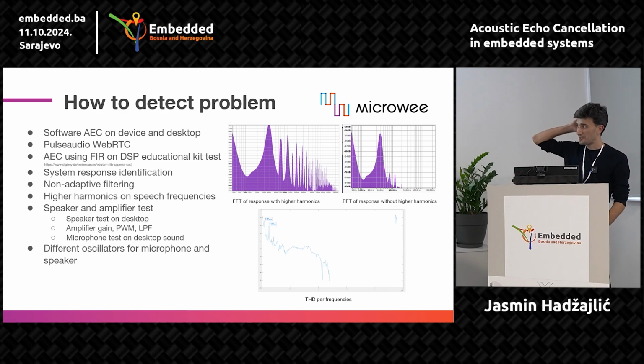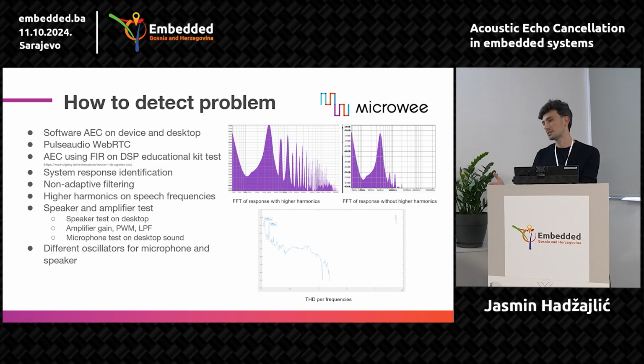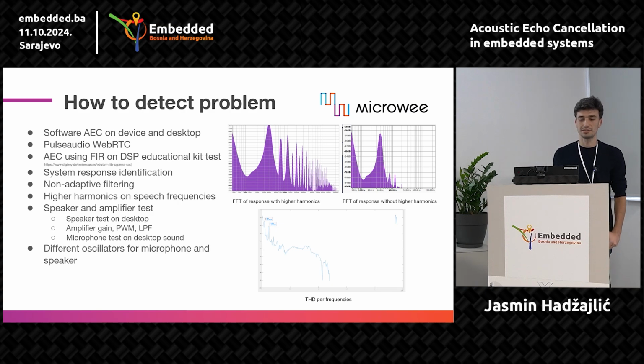Based on that, we did inverse Fourier transformation to get the actual filter, which in the ideal case, or at least, should give us some results. That should be the actual room filter. So we tried to do it hard-coded, instead of using adaptive filtering. When we put that filter instead of the adaptive filter in the schematics before, we didn't get any results. Echo was still there.